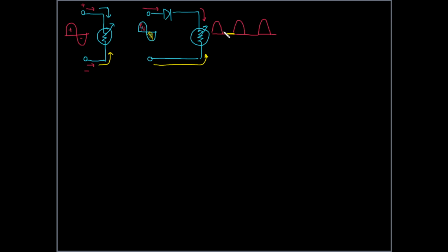You can simply look at this to have an average value, imagining as if it were sand, and you're supposed to flatten that sand there. So that is now its average value. The average value of a half wave rectified sinusoid is equal to its maximum value divided by pi.